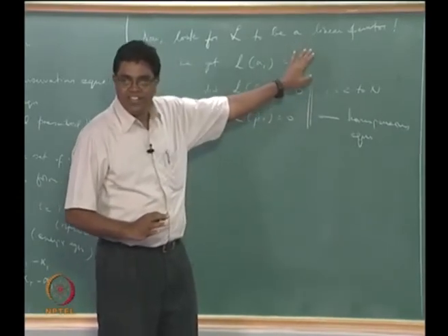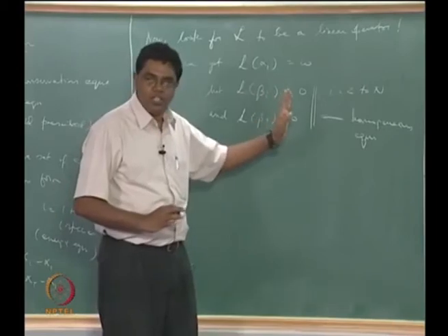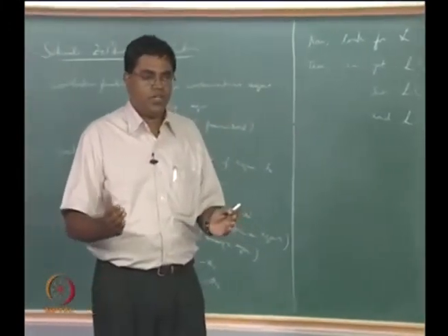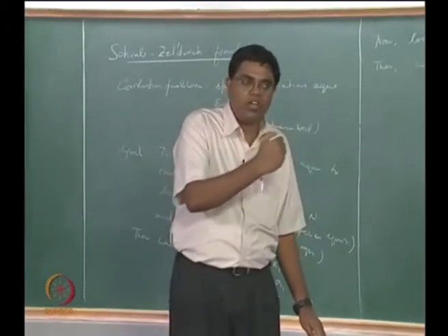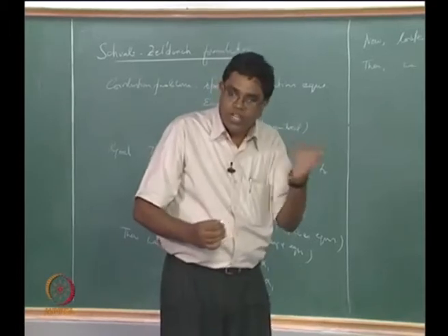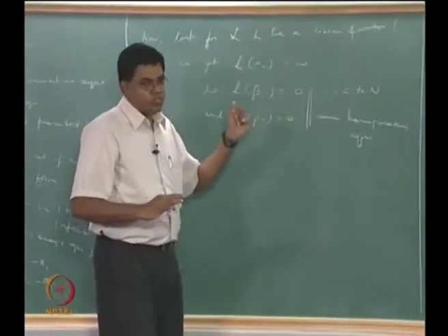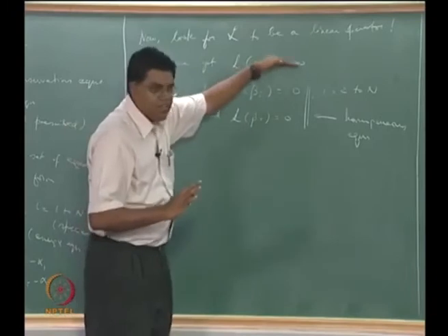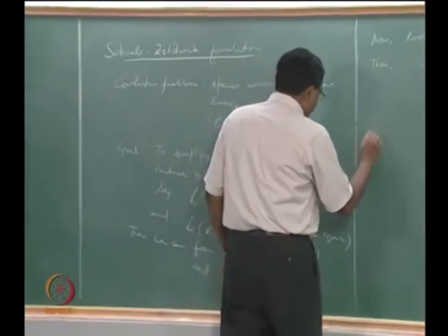It was the right hand side that was nonlinear. We had this exponential of minus E by RT, which was a huge nonlinear term. I am trying to get rid of this in most of the equations. That was posing this stiff problem, right? That was the one that was trying to vary in a highly nonlinear fashion. That means it becomes very sensitive within a very narrow range of temperatures, and you have to take very small steps in time or space or both in order to capture that variation near the flame and so on. All those things we don't have to worry about for these equations. You still have that stuck in one equation representing the severity for the rest of the set.